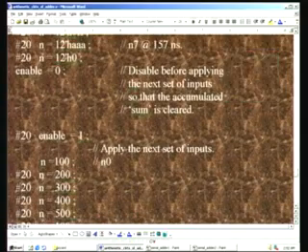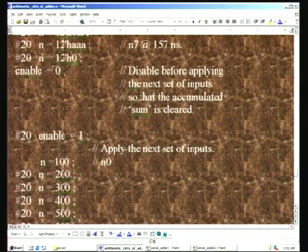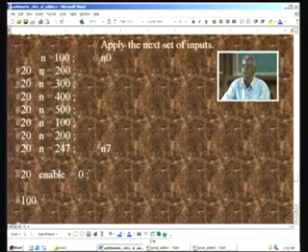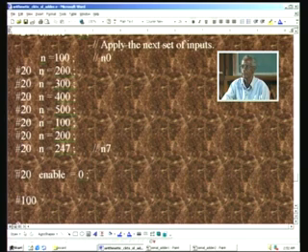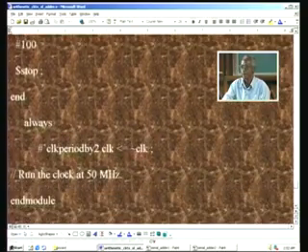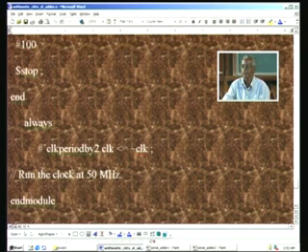And after this we disable for a while, for just one clock duration, and then enable again and apply this second set of numbers here, and you can just remember this one here. Finally, after applying all these numbers for n0 through n7, we disable here, and after about 100 nanosecond we stop, and then we run the clock by toggling clock here, which is once again the same thing we have already seen. This runs at 50 megahertz.